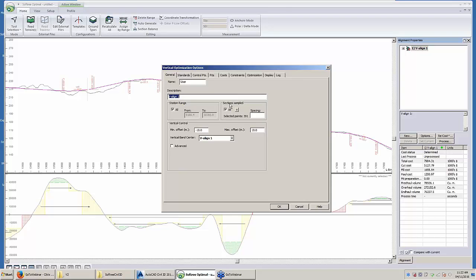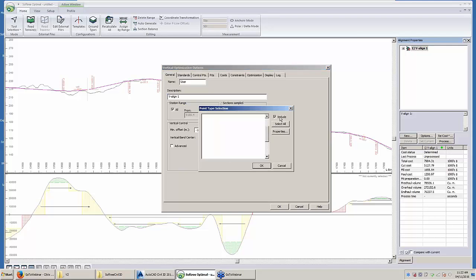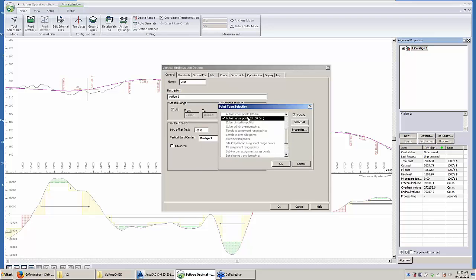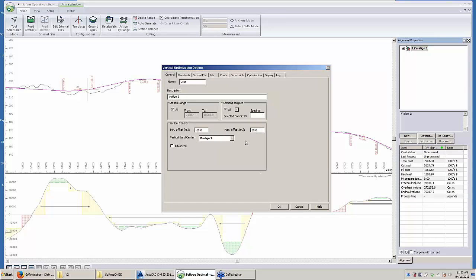We've got sample spacing, and I'm going to cheat a little bit. Forgive me. I'm going to go with a very coarse section spacing, 100 meters. If I go with a smaller one, it's going to take a little bit of time, and I don't think that's time well spent in this demo. Trust me, if you went with a finer, more accurate spacing, you get a more accurate result. This will give us a result, and it'll go faster. So I choose a very coarse spacing.